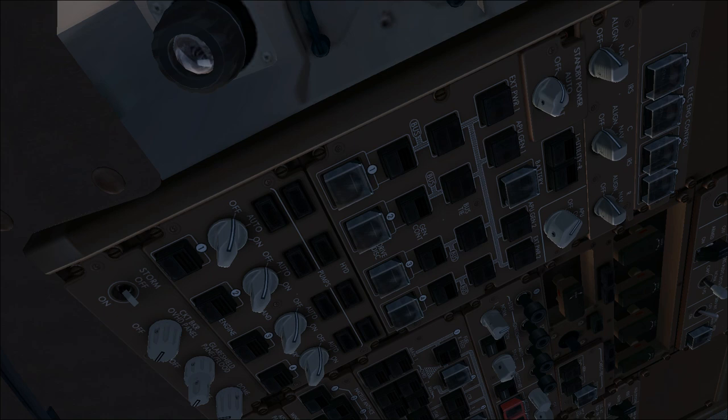With also the essential AC power from the inverters, you will have the left side of the screens, so the captain navigation display and PFD, and the upper view, and you will also have the left control display unit, or CDU, in the pedestal, but I will show you in a few moments. First of all, we have to start up the battery and check that when it is on there are no off lights illuminated, so we open the cover and we turn on the battery. At this point the battery is turned on.